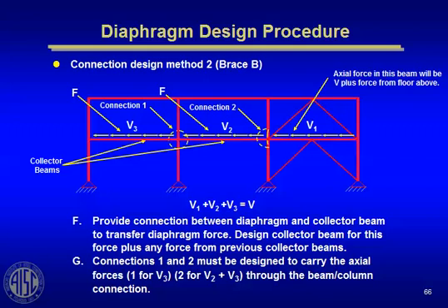Now in those conditions, you got to be real careful that when we deliver the diaphragm shear into that beam, it goes through the connection into the column, out the other side, and the connections are able to carry that, because that's how the load's getting over to the brace frame. So that's why you got to always create a load path in your mind on these diaphragm shears to be sure that all the collector beams and their connections are able to carry these shears.